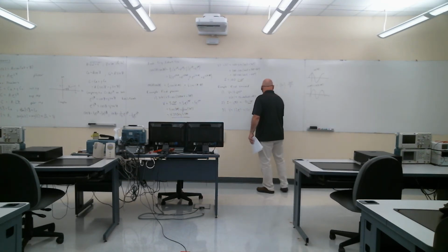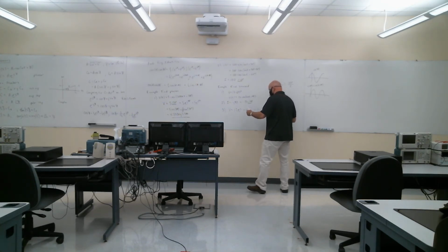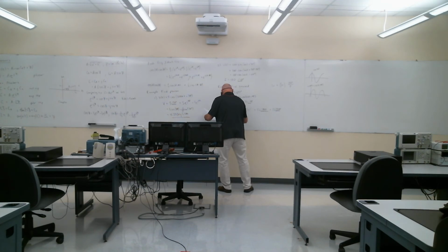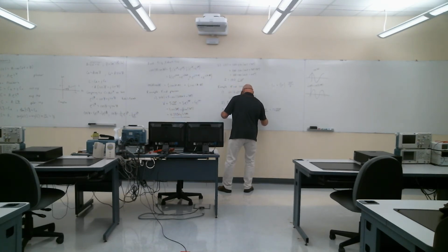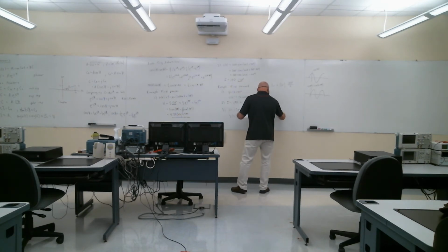So this would actually be in degrees 180 over pi, or 12 at 57.30 degrees. So v of t is 12 cosine of omega 0 t plus 57. I'm sorry, I wrote 53, but it's 57.30 degrees.